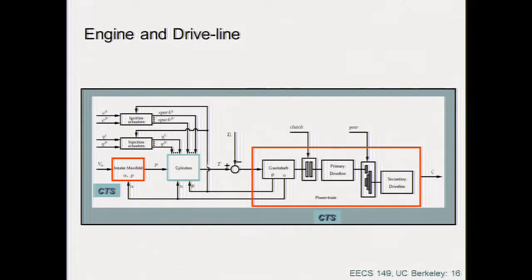But this is a side effect, which is a negative side effect if you do it too much. And this is called knocking. Have you ever heard your engine, I mean the old engines, when it goes clink, clink, clink, clink, that's bad, right? And so essentially it's when you are in third gear and you're going 1 kilometer per hour, when you clank, clank, clank, clank, and the thing is that the gas is actually auto-combusting, right? So it's the spark, it doesn't do anything, and so you get the spark in the wrong moment, and you destroy your engine, okay? Not good.